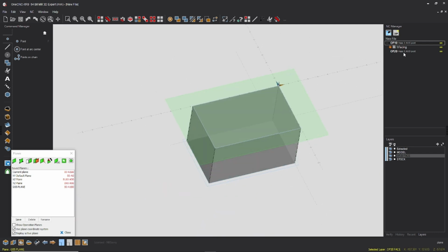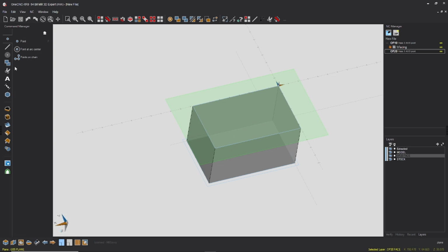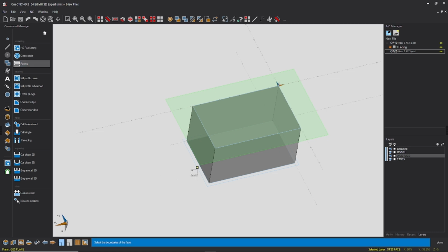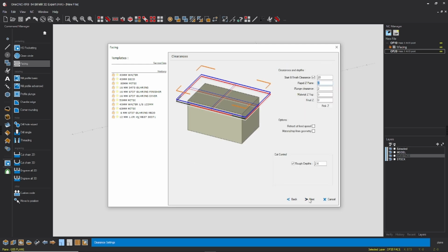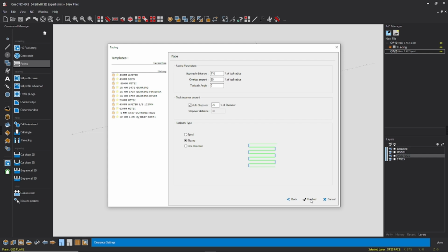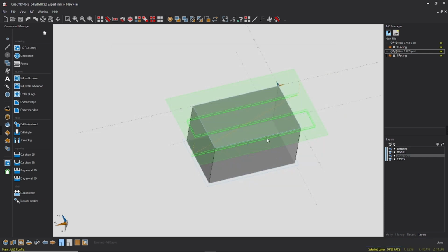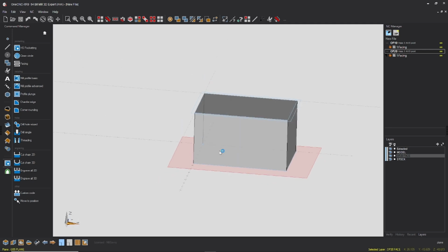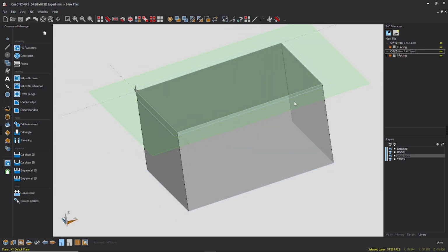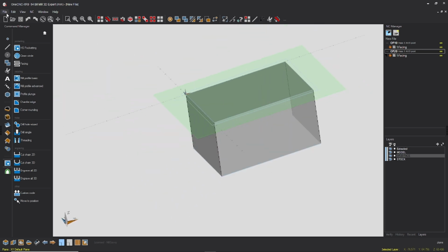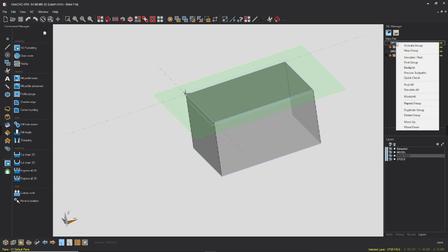So let's apply some toolpath to this. We're just going to face this as well. When we're going down here, face, I can grab this down here, it's not a problem. This is my datum that's activated up here, so it doesn't matter if the line's not on the same height, it'll do it. I know on the first one that was G55 as well, so we would definitely have a problem if we posted this. We'll leave all this the same, just for an example. Now what I'm going to do is quickly flick that back into my default plane. Don't have to, but I will for this example. Put that like that. And this is a good point to save it. And I'm going to simulate all.